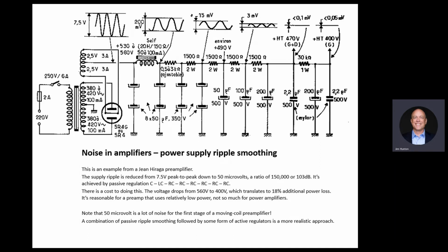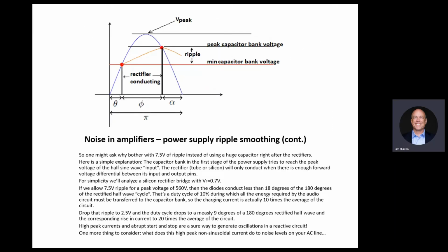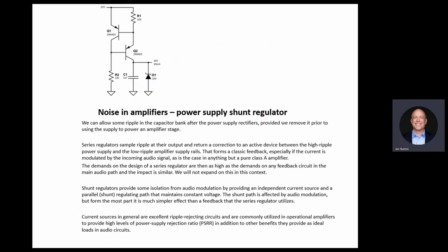It's still there. You can tell. You can reduce it with other circuits, which is not here, but that noise is there, and you want to isolate it. That's why we talked at length about power conditioners and ferrites on power cords. If you have a supply like this particular preamp, you'll notice that your ferrite almost does nothing because there's nothing going on in noise from the supply. So we're getting into the real life effects that we've all seen. We just didn't understand why. Well, there you go.